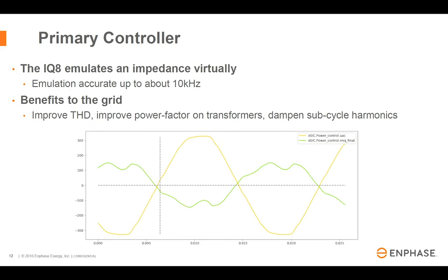I turned on the grid forming controls on a battery inverter, and two things surprised me. One is the THD in my house did improve because I was supporting some of the harmonics in that lateral, so I got better THD. And this is what really surprised me: I got a minor improvement in the efficiency of my inverter, very minor. I thought if I'm providing harmonics, you'd expect the efficiency of the inverter to decrease. But in this case, the third harmonic flattened out the power curve a little bit, so the inverter was able to support that energy more efficiently. It's a kind of win-win-win.